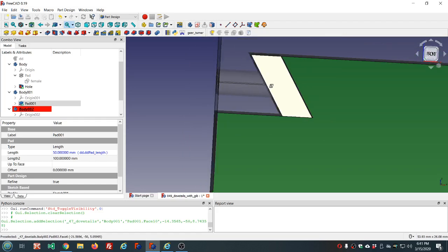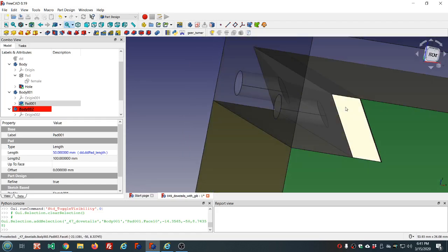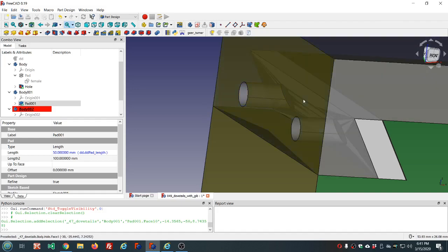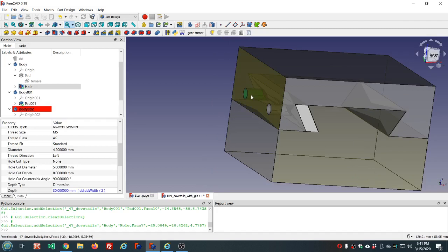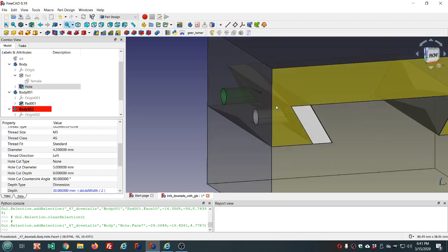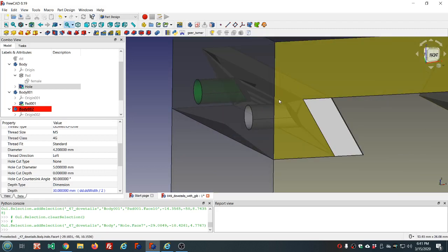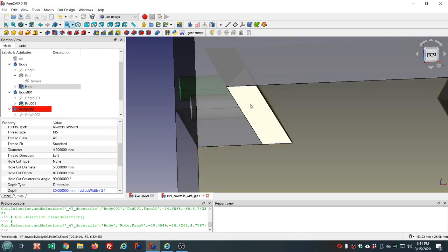Alright, now we need to cut holes in this thing, but we don't cut all the way through. So the idea here is to have some screws going into here. This will be threaded. We're going to thread that after we make it with some taps. I'm not actually going to make this. Just pretend. And so it'll screw into here and go up against this gib and push it against there.